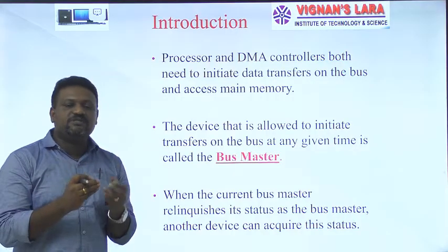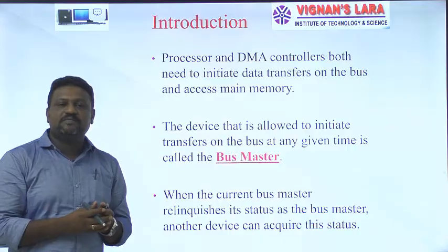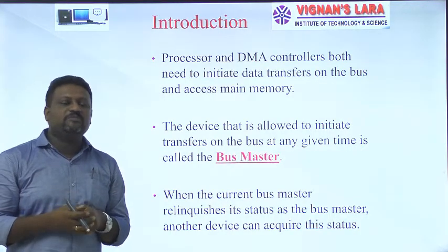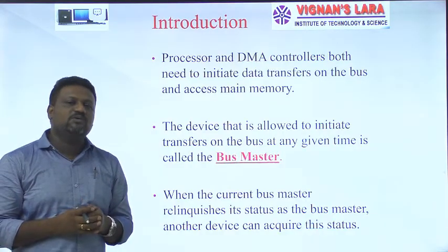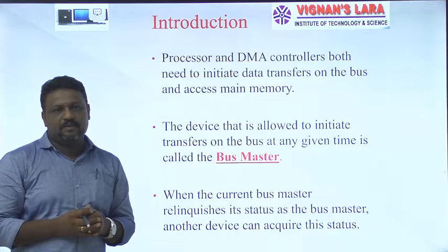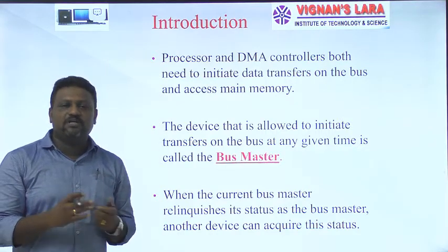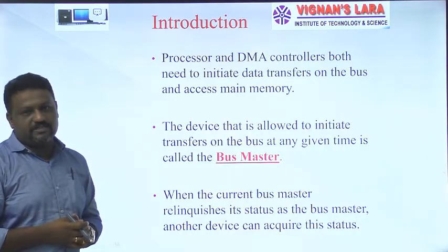Once the CPU receives that request, it gives it the highest priority and immediately responds by sending an acknowledgement back to the corresponding device, as well as releasing control over the system bus. Later onwards, the system bus can be used by the DMA controller. It can provide communication between an IO device and the memory elements.